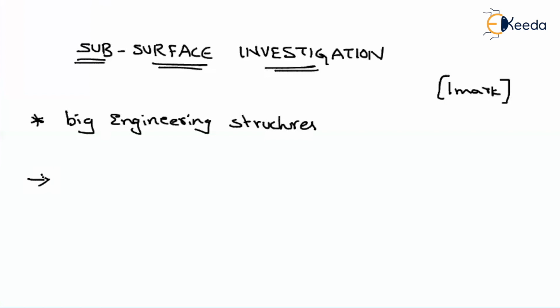Okay. Now, normally, why do we have to study the subsoil? Because we will first study what the type of soil is, whether it is a gravel soil, a sand, a silt soil, or a clay soil. That means depending upon the different type of soil, they exhibit different properties. And also, we have to find out the depth of foundation. That means up to how much depth we have to construct.